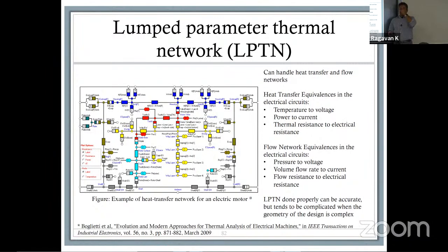Your electrical equation has to be coupled with the thermal behavior to create an outcome that loops back and informs the system: if the temperature changes, here's how much resistance is going to change. Which means our control algorithms have to take into consideration certain terminal measurements. You might only have voltage and current as terminal measurements, and that's good, but you have to start looking for a signature that goes beyond what the harmonic or the THD is going to be, right? You have to start looking at, is there a fluctuation? Can I take a second differential of the current, d2i/dt squared? Does that give me information? Fault isolation. You can look at all of those things specifically from the perspective of terminal measurements that are currently available.